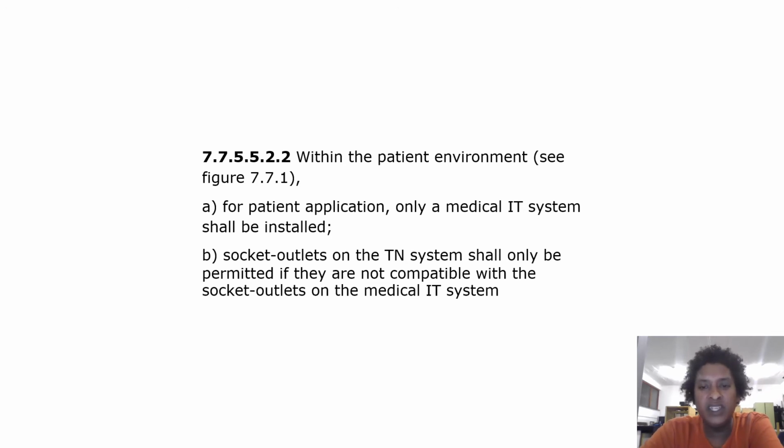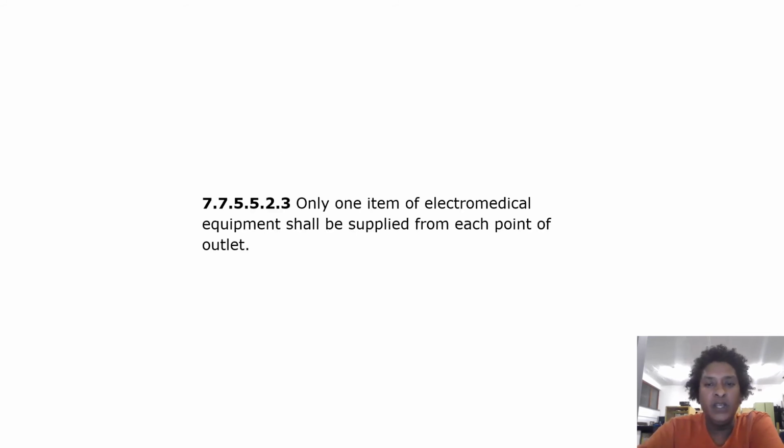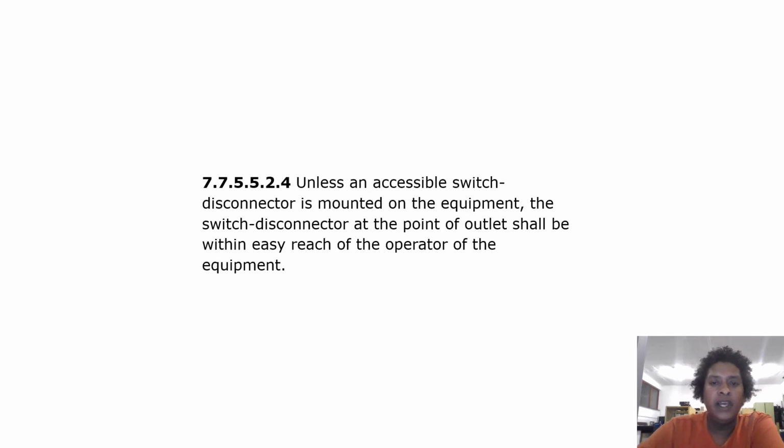Socket outlets on the TN system shall only be permitted if they are not compatible with the socket outlets on the medical IT system. Only one item of electromedical equipment shall be supplied from each point of outlet. Unless an accessible switch disconnector is mounted on the equipment, the switch disconnector at the point of outlet shall be within easy reach of the operator of the equipment.